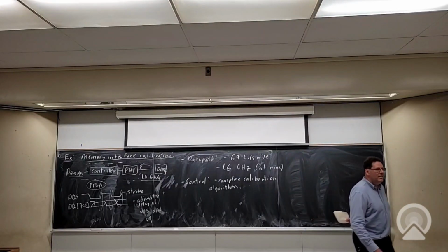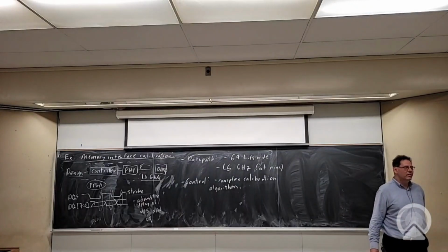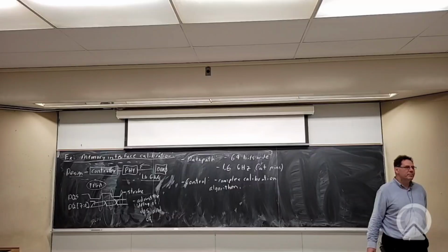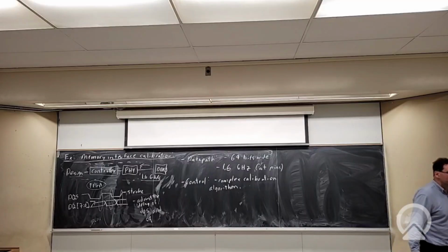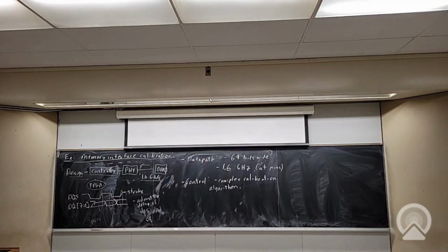Because there's two numbers now. When you're buying RAM, there's the headline numbers like the 3200 or 3600, and then there's a CL, which is column latency. You're talking about CL? Yeah. CL is, okay, so now you're getting into the internals of a DRAM chip. I told you that when you actually read from a DRAM, you have to do it in two phases. There's what's called the activate command, which basically reads an entire row of data.